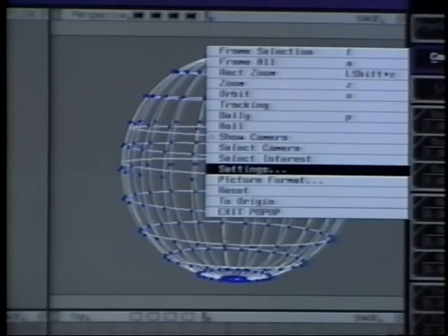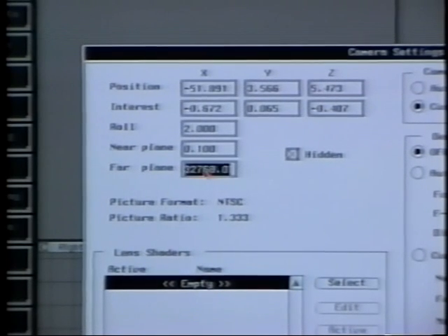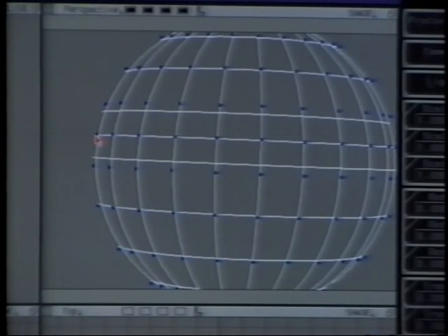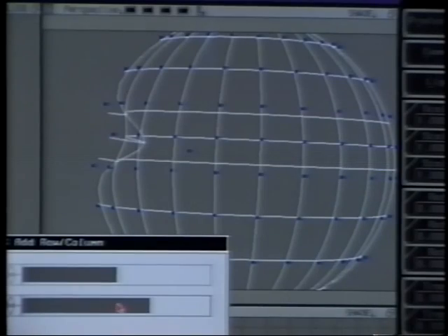Setting the camera's clipping plane closer can hide the backside of a surface to help us see what we're doing. Now, features such as eyes, nostrils, and sometimes mouths when they aren't at a pole in the geometry are very hard to draw into cross-sections and are usually best modeled by plain old-fashioned point dragging. You might need to add a point or two to start with so you have enough to define your form.